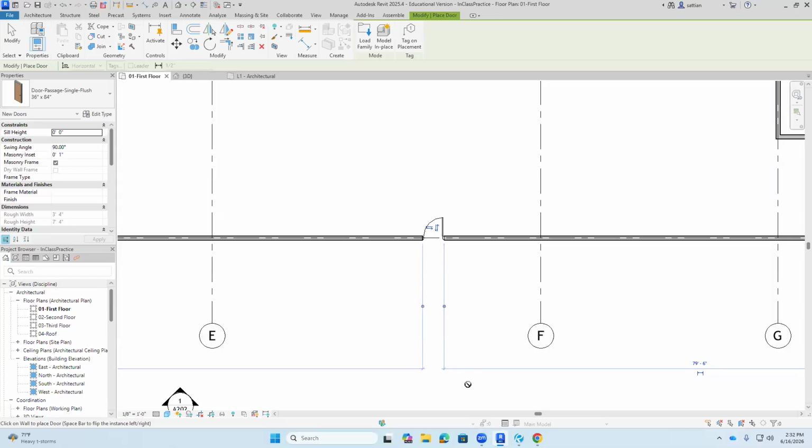Right? Now, when you have massive windows like that, most of the time that's a curtain wall manufacturer that will do that. If you have smaller windows that are punch windows, you get it from a window manufacturer and then put them in place. But those are curtain wall windows. So I'm gonna show you how to do curtain walls, and it's the same idea as a window. So what I want you to do is save your file, close it. Because you're not gonna remember unless you follow along with me. Save your file, close it, and then let's start a brand new file. And I'll show you how to do curtain walls.